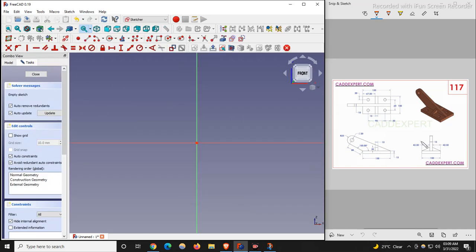First I will make a solid rectangle with the mid plane extrusion. I will make this profile, and dimension is given here with extrusion of 100 mm, and with 150 and 15 mm thickness.